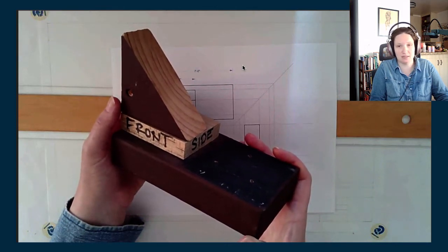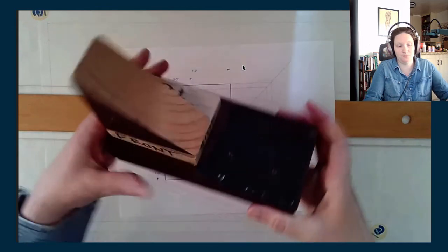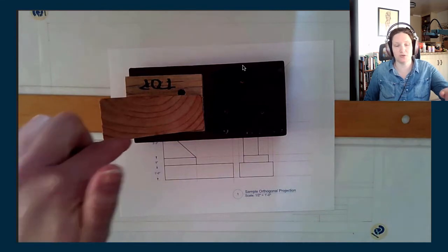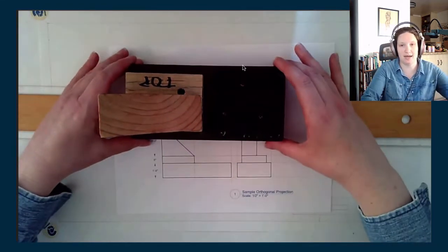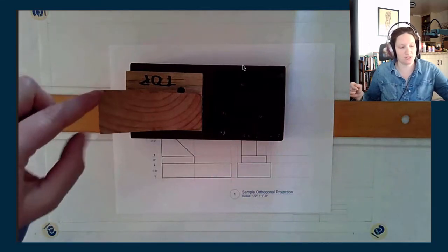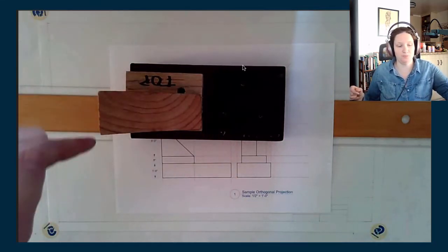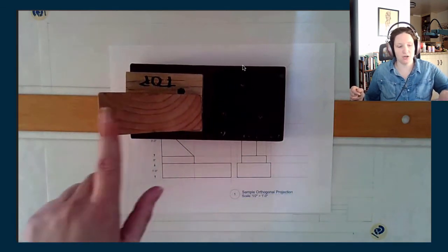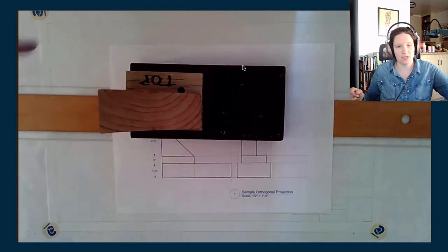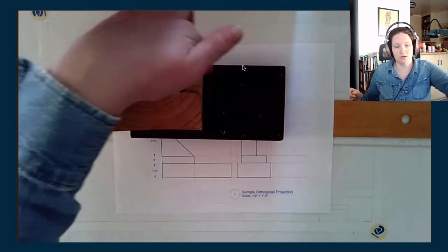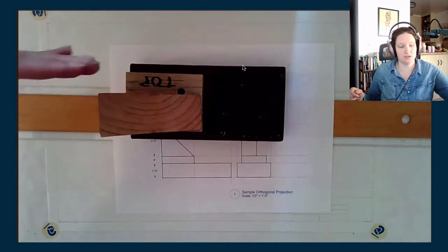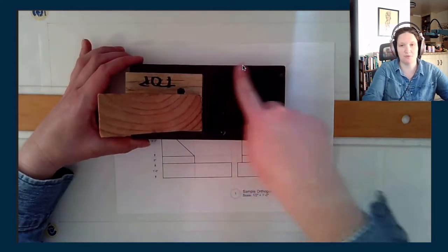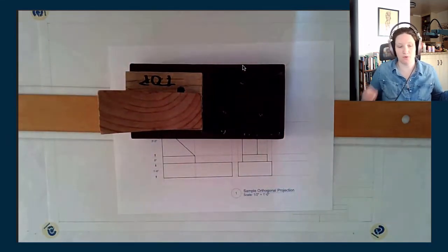So in this case, right, we start with the top view. Boom, the top view, right? And so we look for the lines that we would see looking straight down on the top of this block, right? So it's going to be a rectangle here for our slanted miter cut piece of 2x4. Then we see it's a rectangle here that looks like it's right next to it for this piece of 1x. And that whole thing is floating on top of this rectangle for the 2x4, okay?